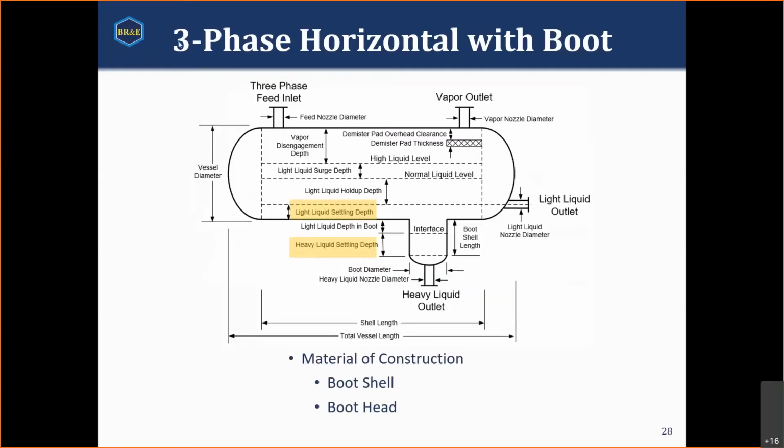And the other three-phase separator that we're going to look at is going to be with a boot. So here we still have our light liquid surge time and our light liquid holdup time parameters represented in terms of their depths, and we have a smaller portion for our heavy liquid, and that's still going to get a settling depth as well as the light liquid, so we still need our residence time specifications in this case.